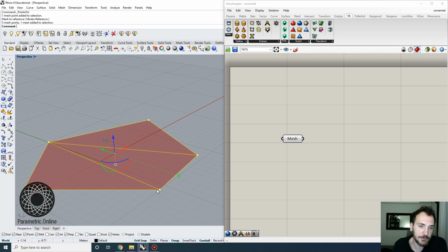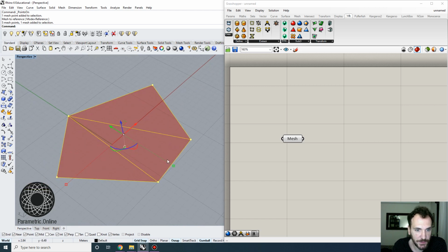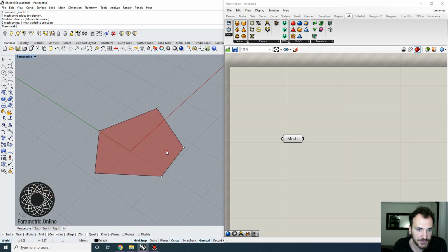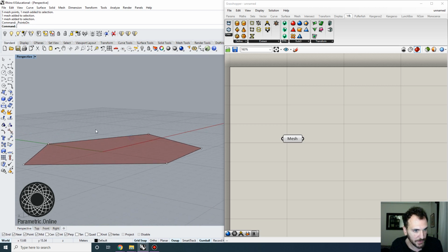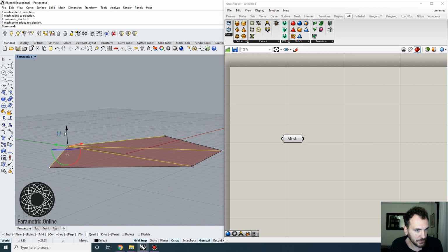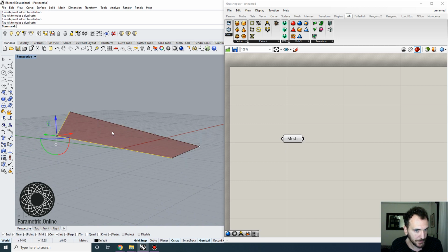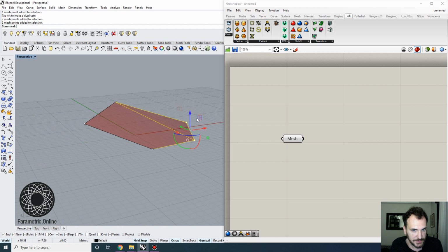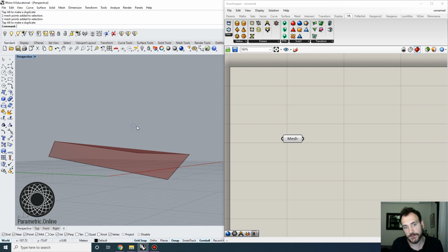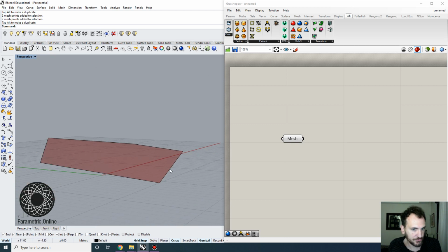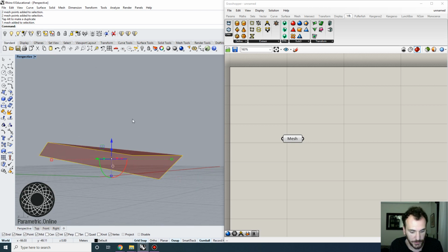In this case, the mesh surface is automatically translated into triangulated data. So you can see that we have 3 triangles defining the pentagon type of shape. And I'm going to hide this. Actually, let's make it a bit more interesting. So I'm going to turn the points on and move these vertices up and down so they all have different z coordinates. And we will try to turn this into a smoother shape using the Kangaroo tool. So that will be the point of this exercise.